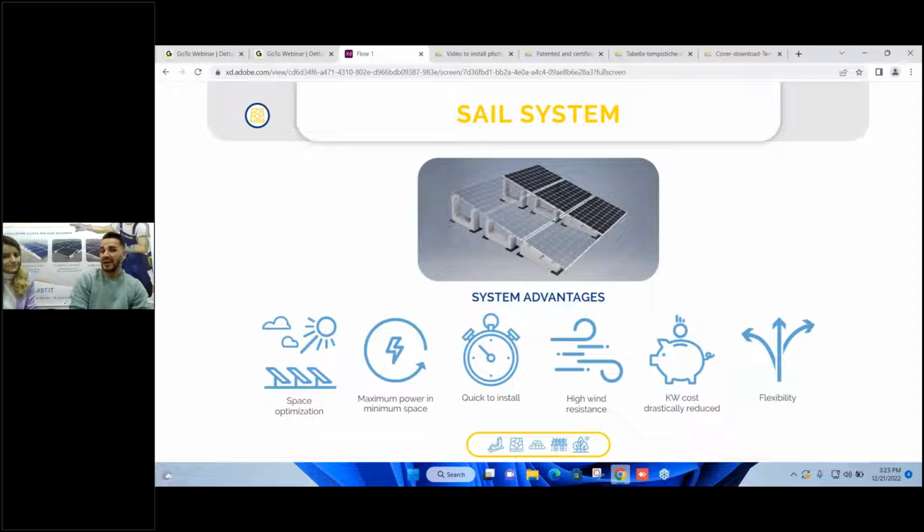There are occasions when the junction plate is not necessary. That always depends on the dimensions of the model that you're using. One thing we'll mention for the laying of the modules with 5 and 11: on 5 degrees, it's possible to lay your modules in vertical poles as well, for standard modules, meaning modules that are less than 2 by 1 meters. The standard modules you can implement with 5 degrees on vertical. 11 degrees, it doesn't matter, standard or large module 2 by 1, they are always implemented in horizontal poles.